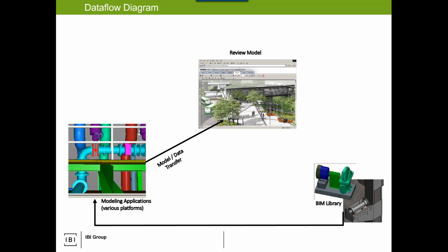You look at it, you clash detect it, you query it, you look for soft clashes. We talked about that, I think it was in week 5. So hard clashes, right? The things that are clashing, and then you identify should they or shouldn't they be clashing. And my favorite, beam sits on column, that's a good clash. Beam going through duct, that's a very bad clash. And you identify it, you mitigate it. Column in front of door. It's not a clash, but it's a very bad soft clash. We don't want that.